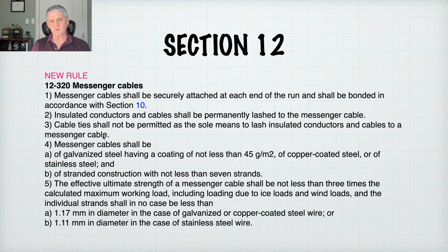If you've ever witnessed, or been involved with a line company or a communication utility, they often have what's called a spinner, and the spinner is pulled along and it actually spins a stainless steel thread all the way around it, which binds it all nice and tightly together. Tie wraps, even the black ones, over time will fall apart in the sun and the heat.